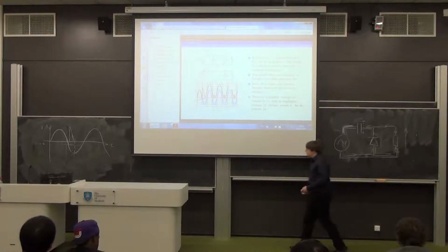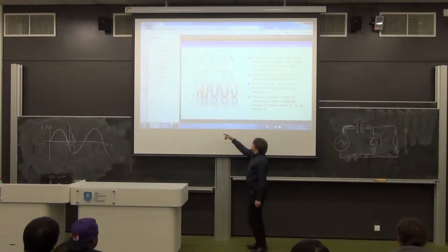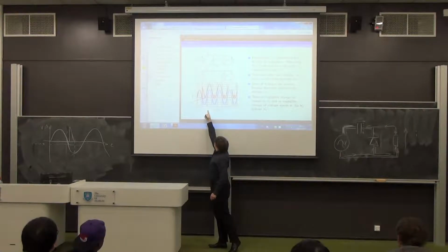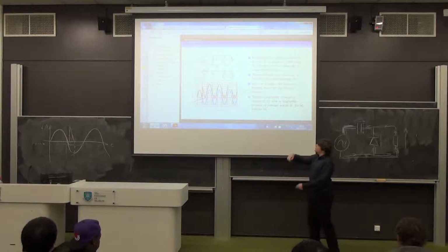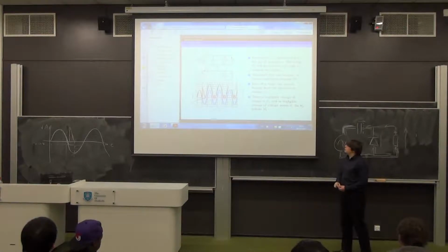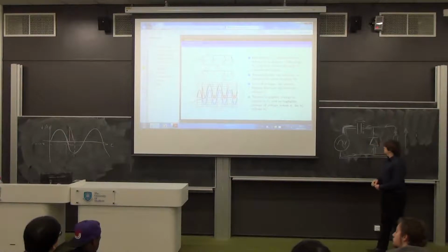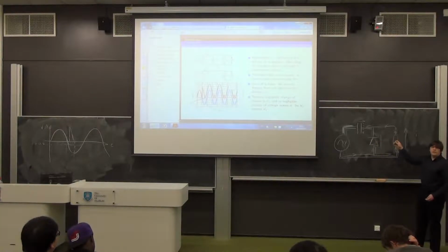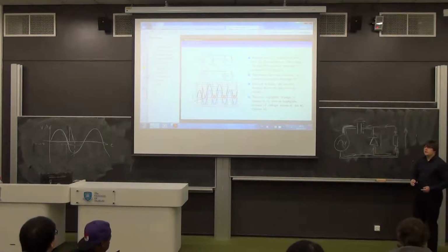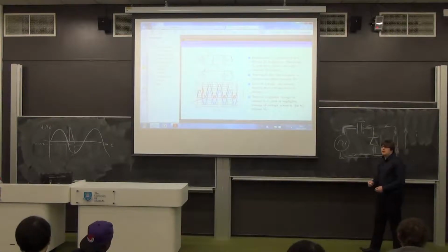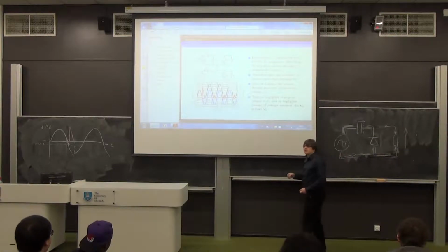Which is what happened in the, well, I might as well just do it up here, look. We are between 0.75 and 1.25 milliseconds. Both of the input voltage and the output voltage, which is black, input's blue, both go up together. And that's just the case of there is no net charge really flowing in the circuit. Very small amount through the resistor, but basically none. And that is the action of the clamp. So you could say that the clamping bit happens in the third quarter cycle, where the diode is conducting and charging up the capacitor.